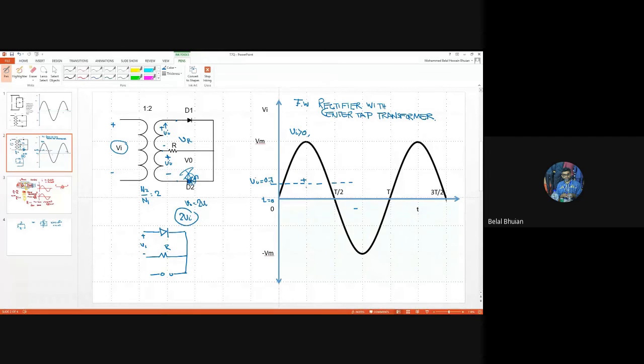And how could we find out which one is the on state and which one is the off state? We said that we keep the signal to our left and check the orientation of the diode. If it is in the clockwise direction, in that case, for all the values of the signal above the transition state line, the diode will be on, and all below will be off. Okay. So we know that above is on, below is off.